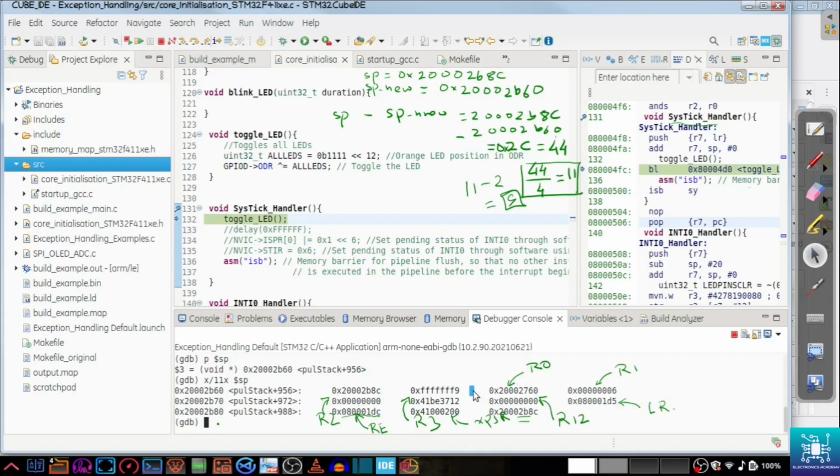It will try to go back to some memory location, thinking that it will take the contents of memory from the stack pointer, which is not a memory address, because it thinks that it is going back, and then it will probably hit some wrong place. It will not be able to access anything from that region, and it will probably throw a memory access fault and so on. So this is how the stacking happens in the case of non-floating point applications.